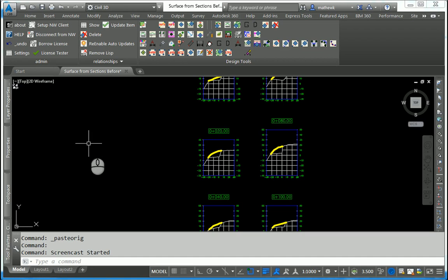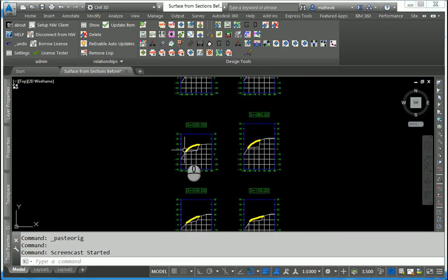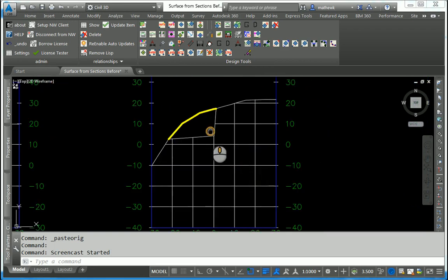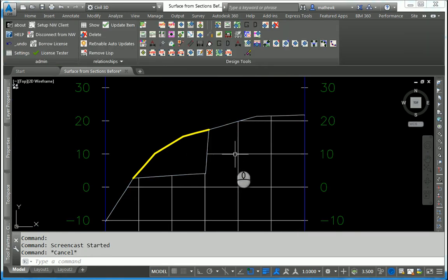In this tutorial, you'll learn how to make a Civil 3D surface from polylines in cross-section. So here we have our desired situation. The white section line is an existing ground section. The surface looks like that. The yellow feature is a polyline just drawn in here for visualization. This is what I want to fill in with material, and I want to be able to calculate the results. So I need a surface to calculate the volumes in Civil 3D.